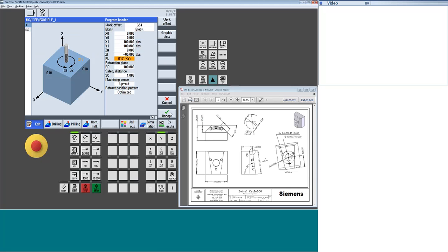Your base tool plane and swivel is always going to stay G17 because I'm going to actually move the unit coordinate system, so the tool is always normal to Z. Sitting parallel to Z, I'm moving Z around and making the tool go normal to that. So you're just going to stay in G17, like you always have.